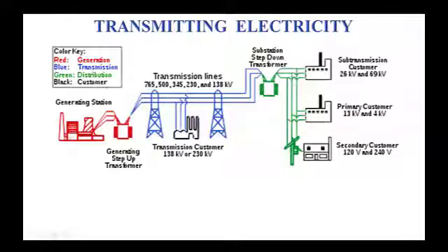So typically what we do is we generate a voltage at the power station and feed that directly into a step-up transformer. And we'll transmit this over long distances to avoid power losses, very high voltage. And we'll talk more about that too in a couple weeks. So I'm stepping up the generated voltage to a high voltage, low current, so that it can be transmitted over long distances without power losses in the line.